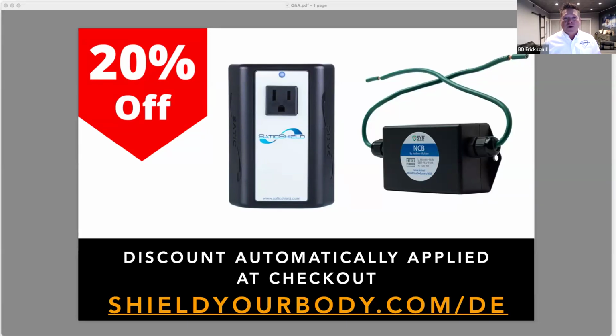Heal thyself a little bit, take what power is within your reasonable power and look at your outlets. Get a little outlet tester. In Satic's demo kits we always send an outlet tester in there. People go, well, what the heck is this for? Well, you might not need a filter, silly goose. Your neutral and your ground might just be reversed. Switch that and you're off to the races. Send the filter back. So yes, wherever there's more opportunity for error is going to be worse, but it's all the same conversation no matter where you live. Excellent. Thank you both.